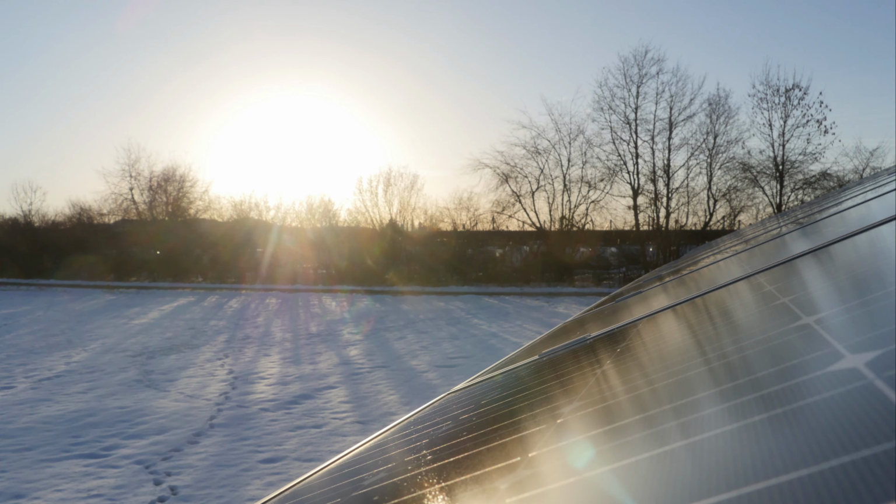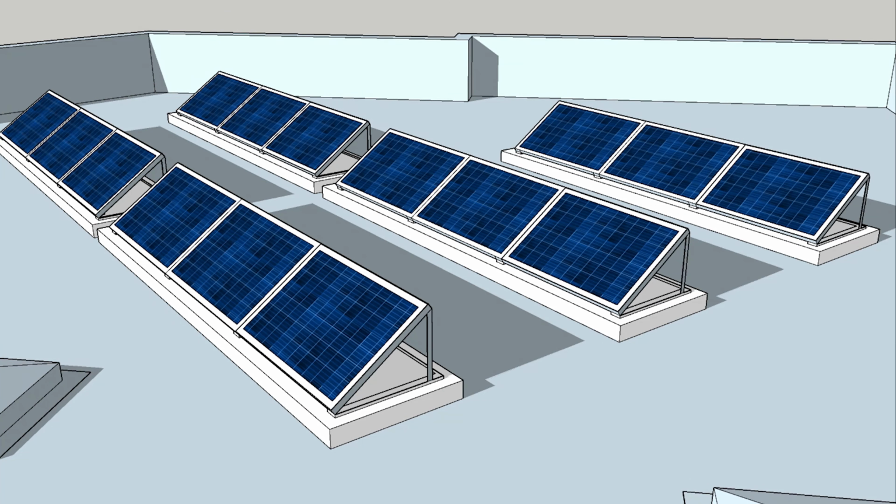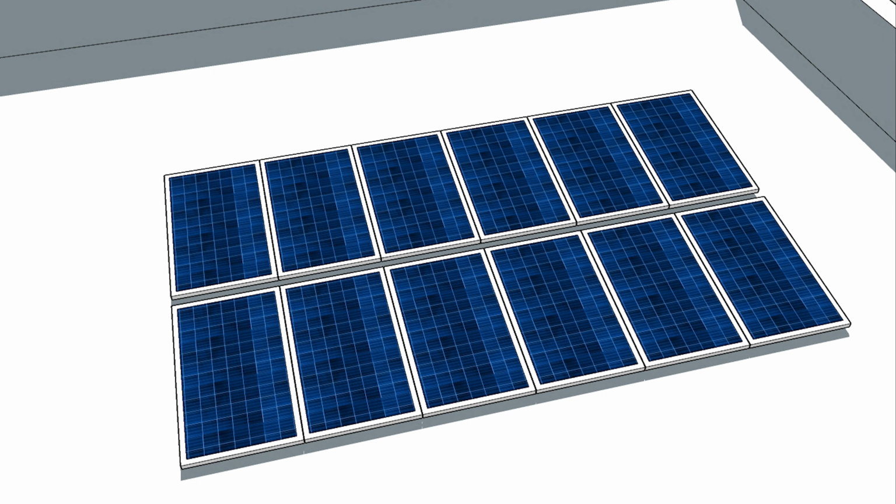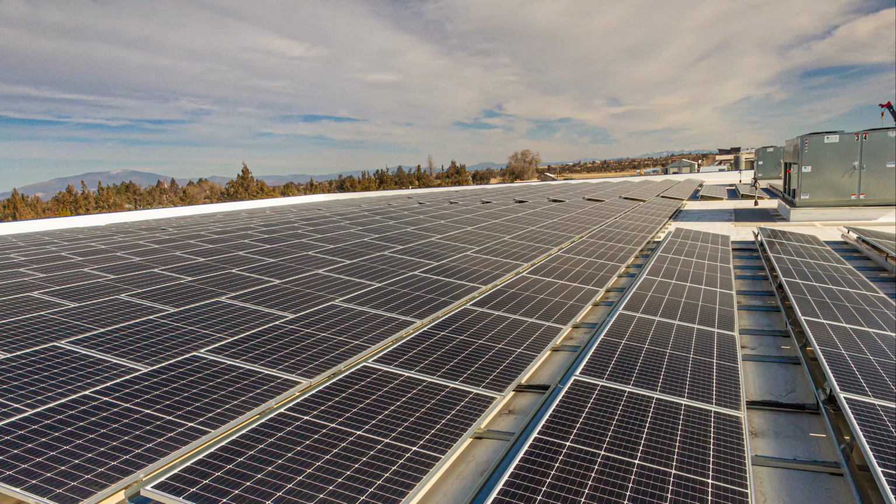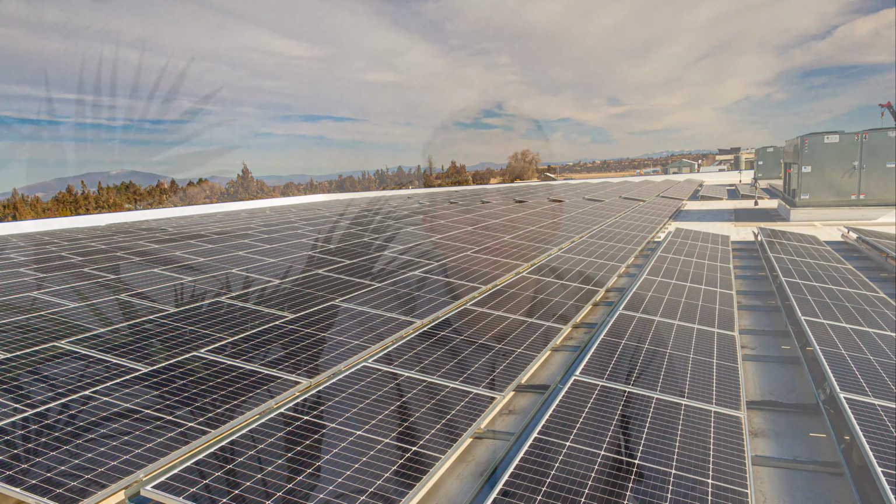Imagine it's the winter time. The sun is quite low for most of the time. As long as it's not cloudy, you're actually best off with the solar modules jacked up quite steeply so the sun strikes them at a better angle. On the other hand, when it's summertime and the sun is quite high in the sky, you want the modules fairly flat. Obviously you could have a fancy system to adjust the angle, or even a setting that you change occasionally, but that flies in the face of the inherent simplicity of solar PV, and it brings a whole host of extra complications that are best avoided. So as you can imagine, there'll be an optimal pitch that gives the best overall energy generation.